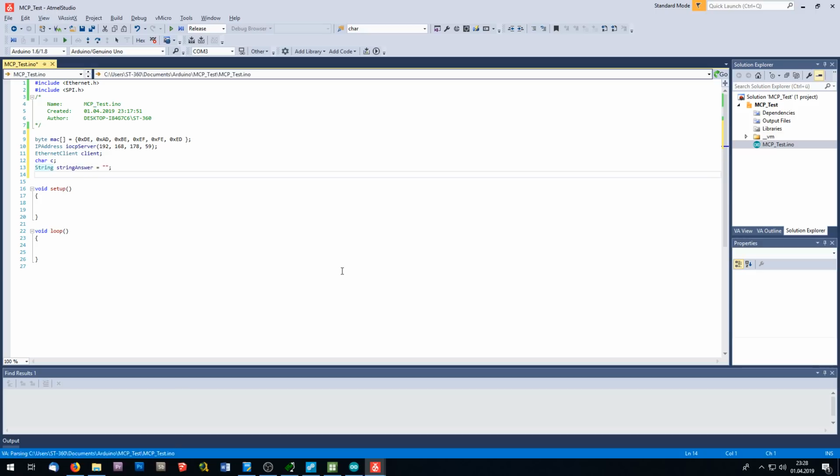And as you know, we will receive variable numbers and values that will be stored also in separate variables. First of all, the number and the value. The state of our switch will be stored in a separate variable. And we define the 2 pins of the Arduino we'll be using. And this will be the pin for the switch, which is on pin 3, and the LED pin, which is pin 2.